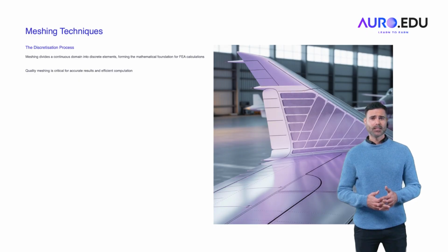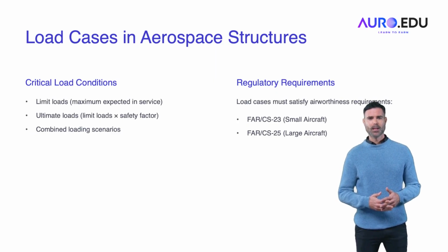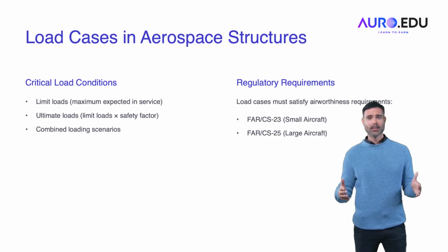Mesh refinement studies help engineers verify the accuracy of their simulations and ensure that the solution is independent of the mesh discretization. Load cases in aerospace structures. Load cases represent the different types of forces and conditions that aerospace structures must withstand during their operation. Limit loads represent the maximum expected loads during regular flight operations, while ultimate loads are typically limit loads multiplied by a safety factor. Combined loading scenarios involve the simultaneous application of multiple load types, such as aerodynamic loads, gravity, and inertial forces.